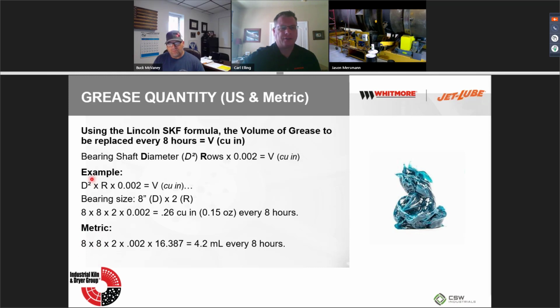So in the metric and as far as conversions, you still use the same diameter. So 8 times 8, that's your D². So your diameter squared, multiplied times your rows, multiplied times 0.002. And then this is your conversion factor to get you in milliliters. So 4.2 milliliters every 8 hours. That's not much. So if you think about it, that's an 8-inch diameter shaft, and you only need this little itty bitty amount of grease in 8 hours.